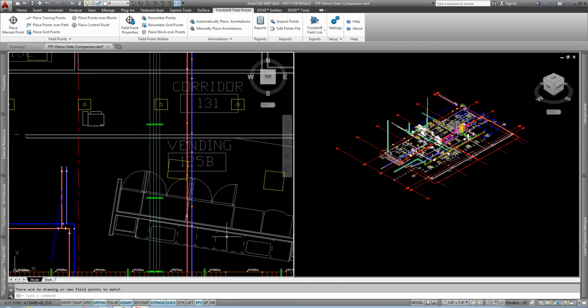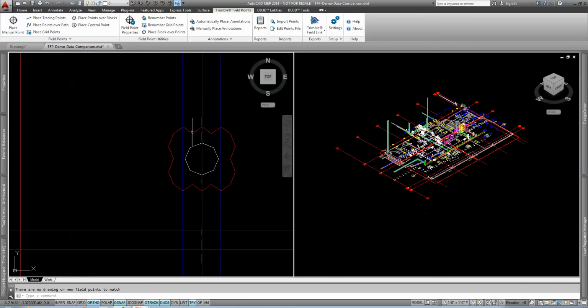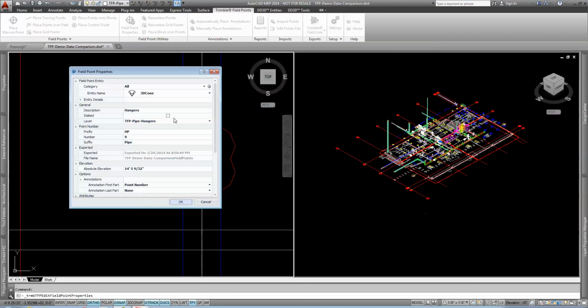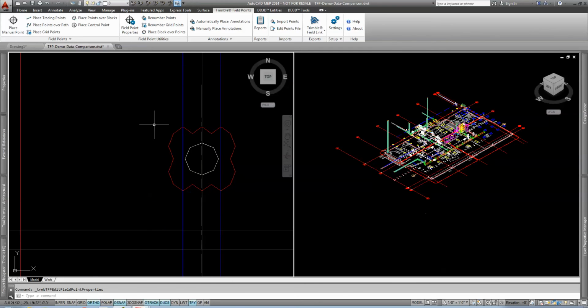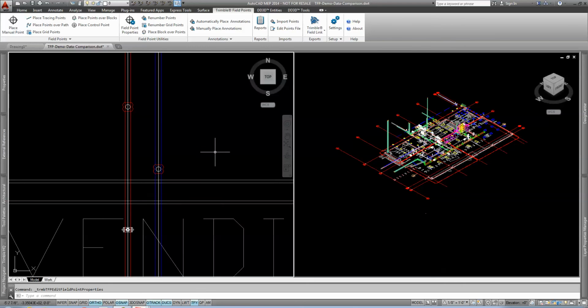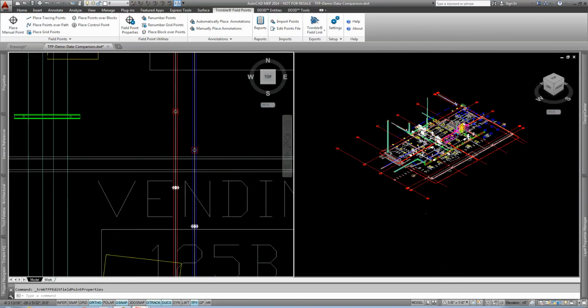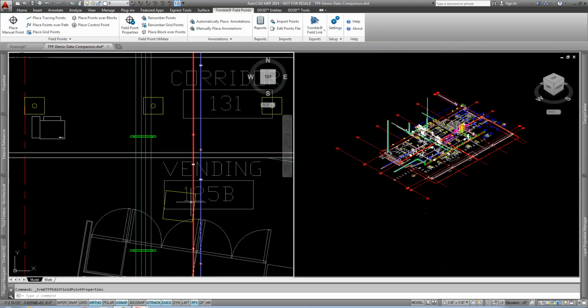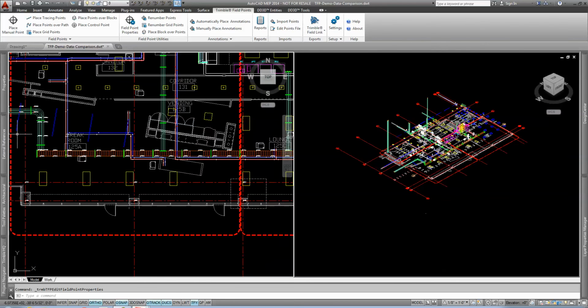I can click on the points and look at the properties. It should tell me they're all staked. Because I didn't do this on the tablet, it doesn't actually tell me that it's staked. That's the only thing right now that's not transferring through, but everything else so far transfers through. And as you can see, you can fudge it pretty good inside of CAD and bring them back in and call it good. Because I just did that for you, you don't have to do it. All you have to do is import that file and it will show it just like this.